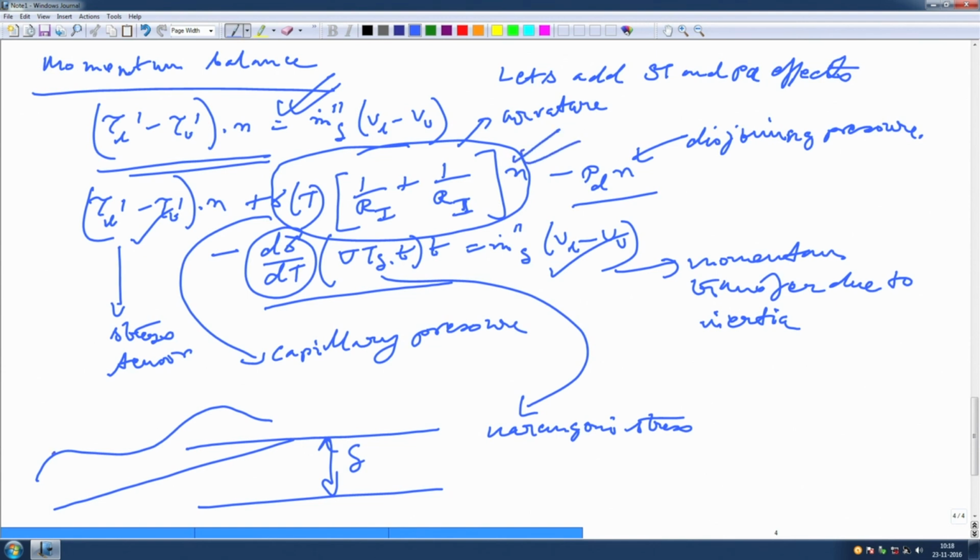If there is a temperature variation from here to here, that can happen because say you have a heater, a differential heat flux, and you are supplying heat to this substrate in this particular fashion. What will happen? This surface temperature will also start to vary. Because of that, you will actually have a variation of the Marangoni stress across the interface, that needs to be accommodated over here, right.